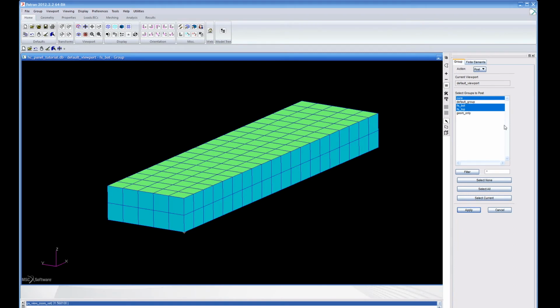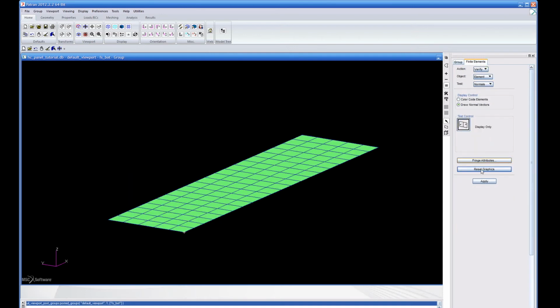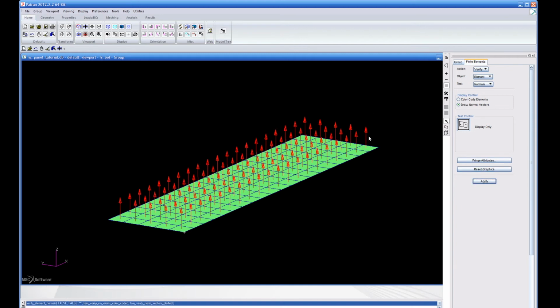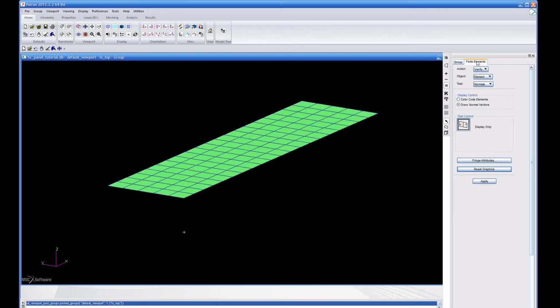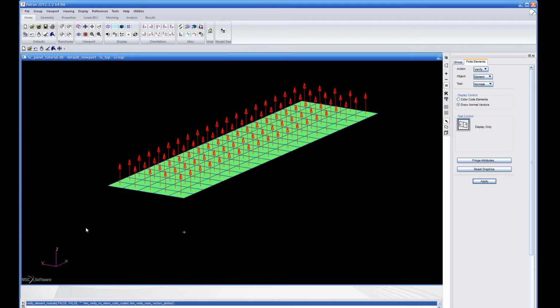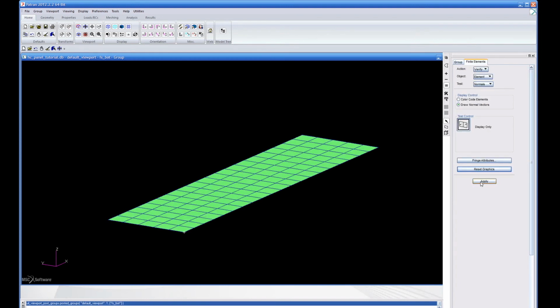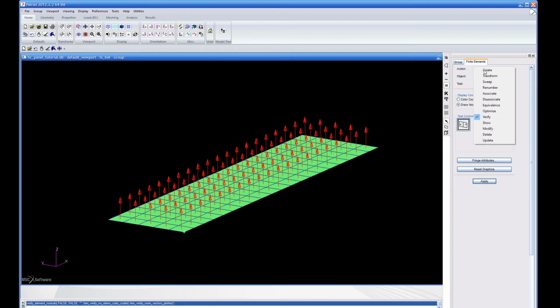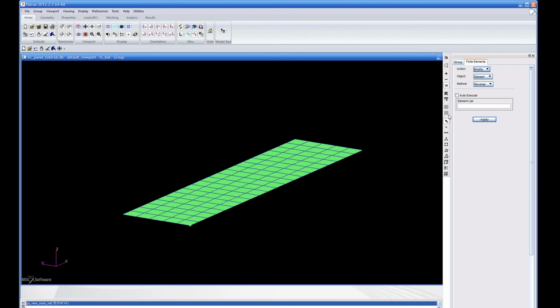And now all our properties have been created and all of them have been assigned to our elements that we've created. The next step is to check the normal directions of our elements, and I always like to have the normals of the elements facing away from the core, and this affects when you're building your laminates for each of the face sheets. It affects the stacking or the order of your face sheets. Now ours are symmetrical, and so it doesn't matter in our case, but when you have unsymmetrical stackings or something like that, the normal direction is going to influence the way the laminate is built.